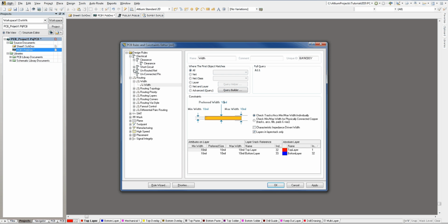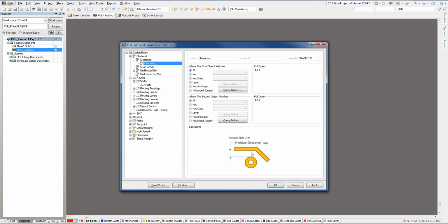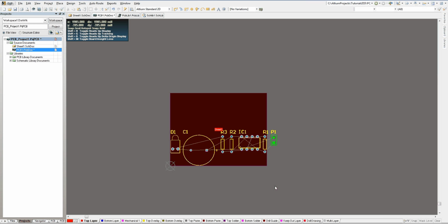You have a lot of different settings in here, but Altium Designer makes a nice schematic for you, so to speak, so you can change the clearances that you want. Let's say you want to set this to 20, and then you press enter, and there you go. You should really go through all of these and make sure that they're correct with your standards as well as the manufacturer, to avoid any overcharges on your orders. So you click apply, click OK, and you're done with that.